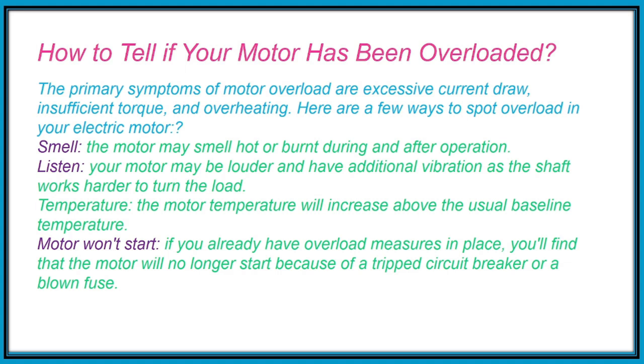Smell: the motor may smell hot or burned during or after operation. Listen: your motor may be louder and have additional vibration as the shaft works harder to carry the load. Temperature: the motor temperature will increase above the usual baseline temperature. Motor won't start: if you already have overload measures in place, you'll find that your motor will no longer start because of a tripped circuit breaker or a blown fuse.